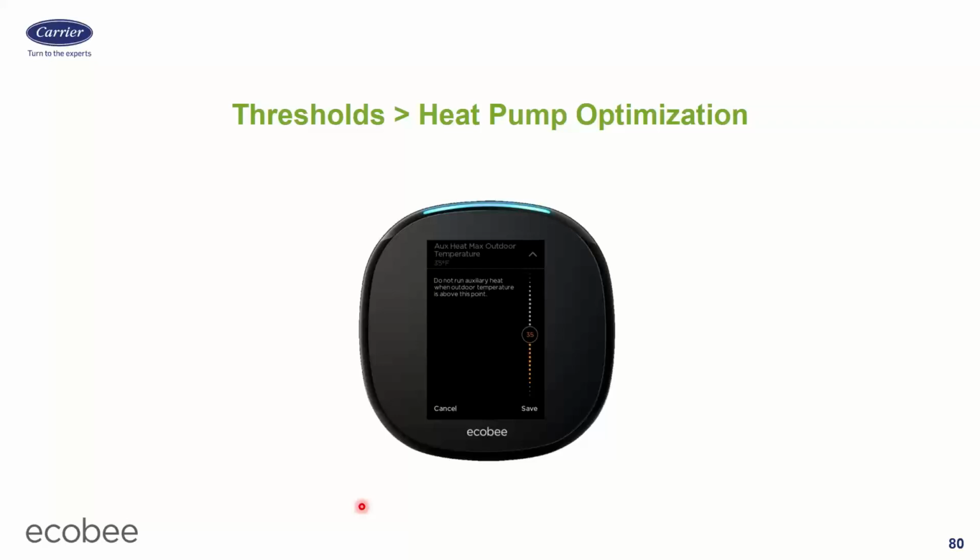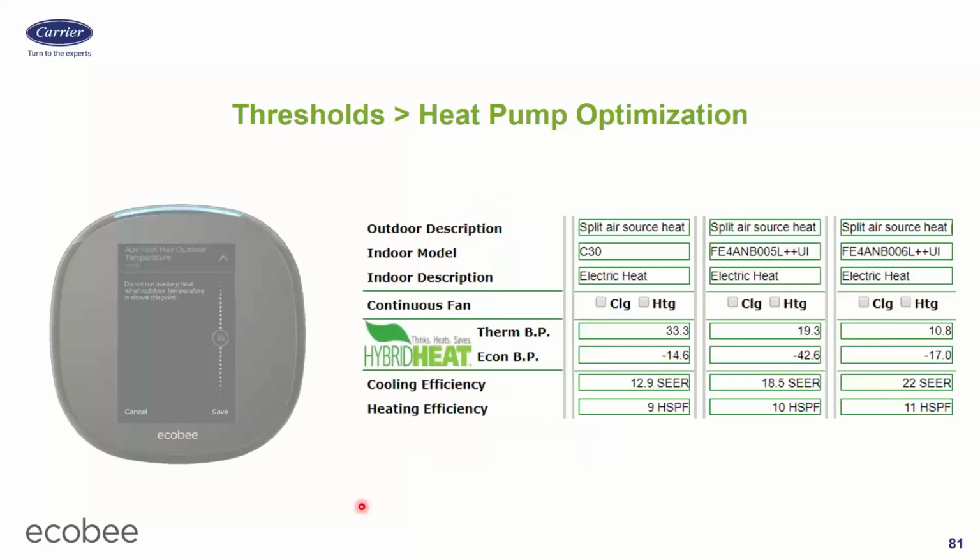What's an appropriate temperature? Well, the good or the bad news is there's no correct answer here. Well, there's a correct answer. There's no singular correct answer that I can give you and say, oh, you always set it for 32 degrees and it's perfect. That's not the case because there's a wide range of what a heat pump may be able to handle. So what I did is I used that same opcost calculator that we used last week to do 3 different examples. And I specifically blocked out the models of heat pumps in this case, because I didn't want you to see those heat pumps and think that's always the answer. Because the answer is not even always the same for every model of heat pump.